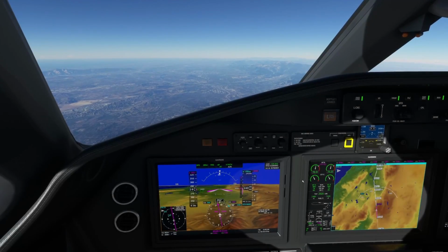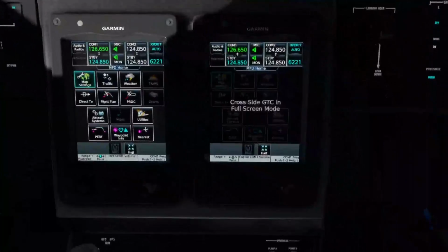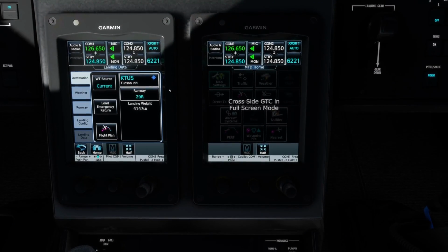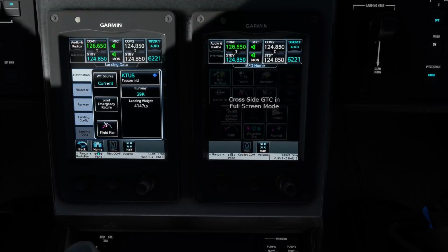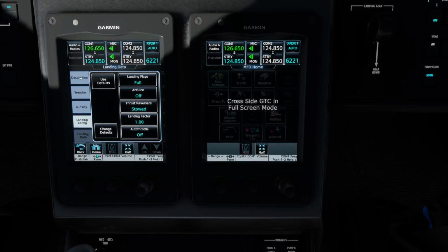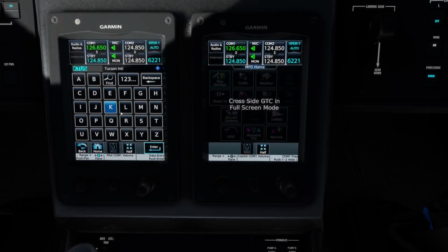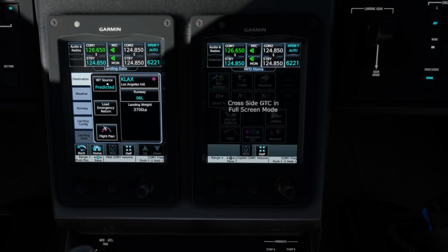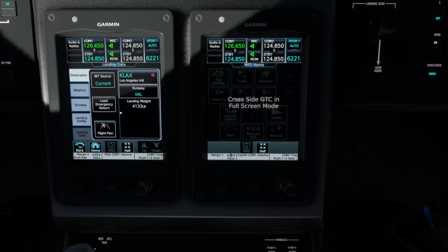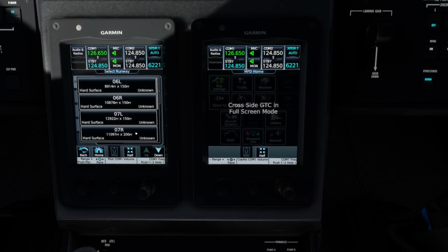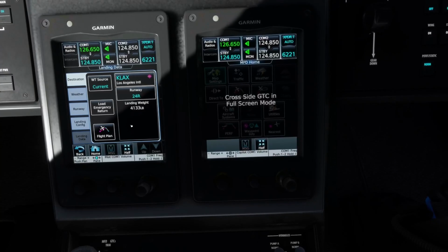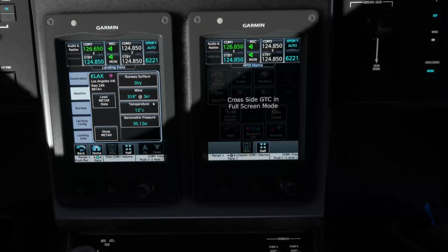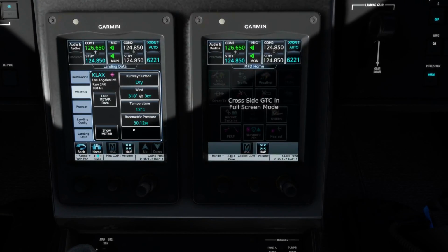Okay, we're passing through 24,000 feet here, and I figured this would actually be a good time to take a look at the performance pages for landing. So let's see what we have to worry about here. Oh, destination. That's not right. Weather. Weather source? What is this? Current? Choose current. And runway, we're going to be coming in on 24 right. Okay. Weather. Load METAR. Look at that. And this time it grabbed the temperature. That's nice. We even got our barometric pressure, 3012.